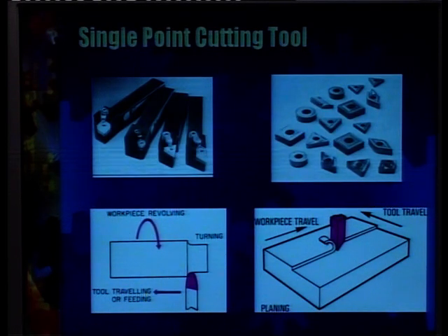One important thing is that these carbide tip tools cannot be reground. They can only be used once in a while. Suppose we are using this type of chip: first we will use this edge of the chip, then the second edge can be used, then the third edge, and then the fourth edge, and then the other side can be used. But ultimately, when all the sides have worn out, it has to be thrown away.